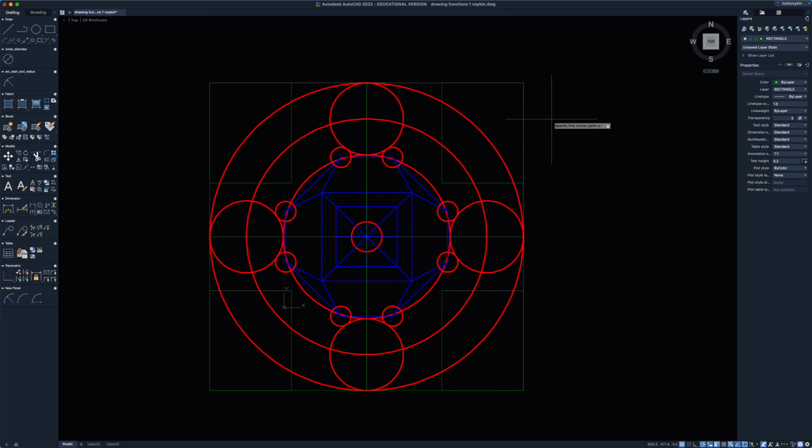and now it's saying let's make that rectangle. So I'm going to do the same thing coming from this corner, making my rectangle right here with those chamfered edges. And chamfered edges are basically just sort of angled edges, so it's almost forming like an octagon shape for us here. Okay, so again, what is the length of the sides? Well, it's 100 and 100. I'm going negative in the x, negative in the y, so I'm going to type negative 100, comma, negative 100, hit enter, and that is done.